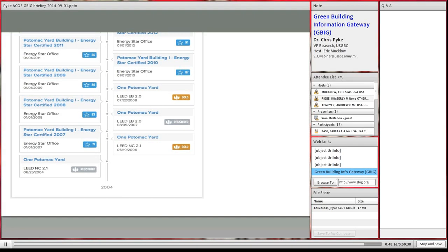We did some studies through our Construction Engineering Research Laboratory in Illinois that showed we could reduce the energy consumption of buildings by improving the building envelope, such that we would then be able to put a smaller mechanical system in the project, so the end budget was actually cheaper than it would have been otherwise. So there's no incremental cost, and of course, to take it further, we would try to get to a point to incorporate everything that was life cycle cost effective.